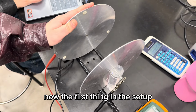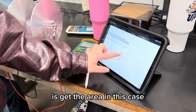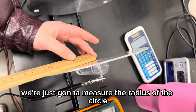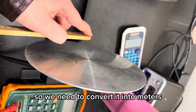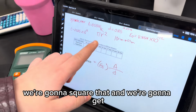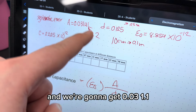Now, for the setup, the first thing we need to do to get the theoretical capacitance is get the area. In this case, we just measure the radius of the circle. We measure it and get 10, but that is in centimeters, so we need to convert it into meters, and we get 0.1. Now we square that and multiply it by pi, and we get 0.03141.